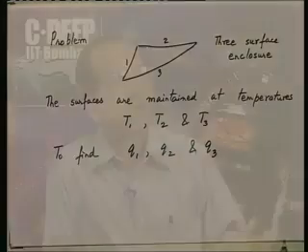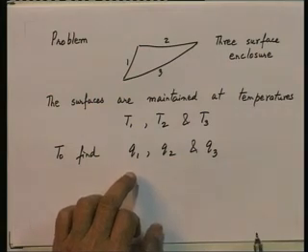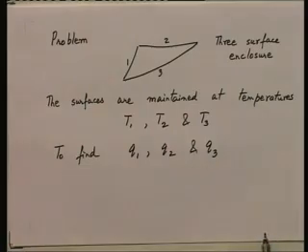It is just the same earlier 3 expressions that we had, but now in this case you know the values of EB1, EB2, EB3. So, you can directly from the 3 equations which I put down earlier get the values of Q1, Q2 and Q3. So, the point I want to make is, for any one of the surfaces, you need to specify either the rate at which heat is supplied at the surface or the temperature of the surface, either the Q for the surface or the T for the surface.